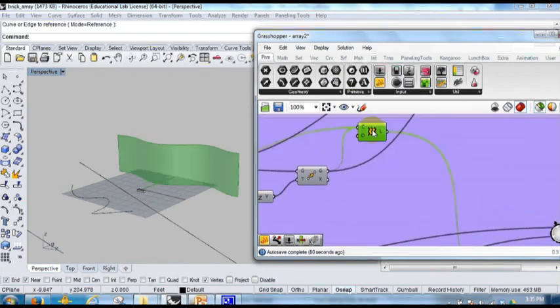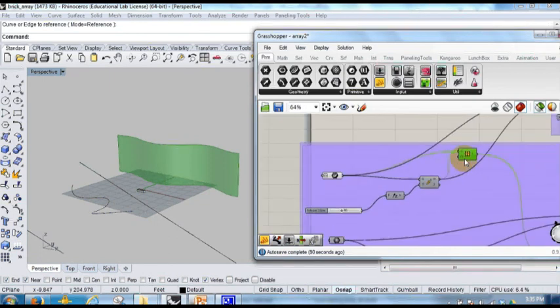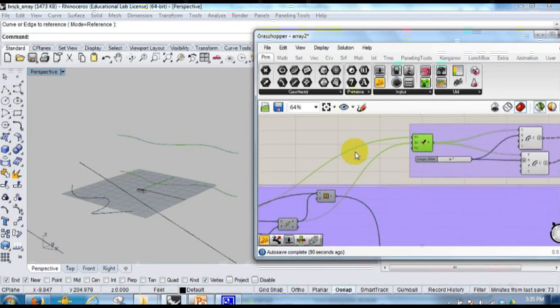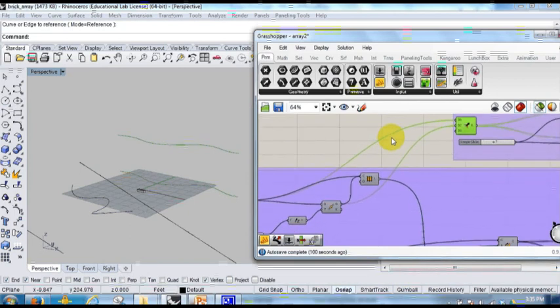This is the lofted surface to populate the break, right? And this surface is exactly the same one I built the top and the bottom from. So they're actually using the same curve. Yeah, that's the reason they match. This is actually pretty interesting about parametric design: one variable can feed into different branches, right? And then you have this kind of coherent correlation between them.